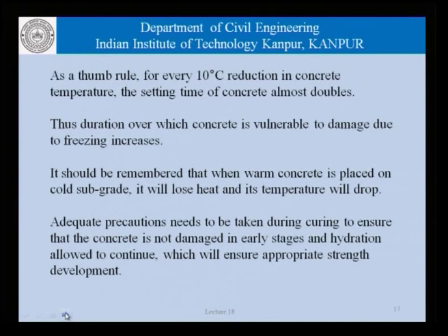Now, as a thumb rule, for every 10 degrees reduction in the concrete temperature, the setting time of concrete almost doubles, as we saw in a previous slide. Thus, the duration over which the concrete is vulnerable to damage due to freezing increases. So long as the concrete does not set, the concrete is very vulnerable to freezing. The water therein is vulnerable to freezing.